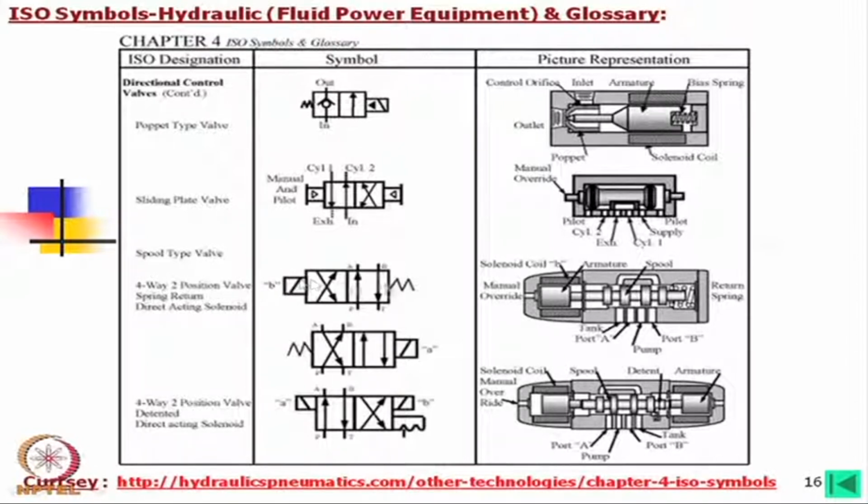So, we can present this valve without these operations also. Say in circuit design, preliminarily we can use only the symbol of these portions, and we may not use this portion because this may be hydraulically operated. So, in the second phase we can select whether it is hydraulically operated and other things. So, this means that when we say 4/2 DC valve, in that case only we will present this one.